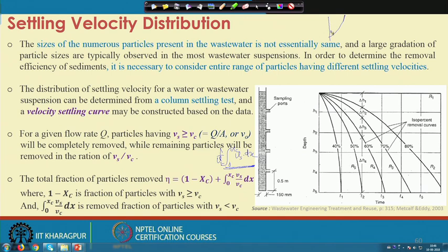a curve like this. So, if we take a small dx and integrate it from point 0 to say x c, this is my settling velocity V s curve. So, this curve, the settling velocity curve, we will get the area under this curve, and in a discretized manner we can take different values of x and the corresponding average value and multiply that in order to get the area. So, that is how we can actually determine the net removal for a varying particle size.